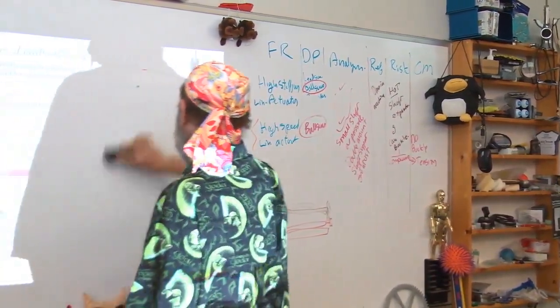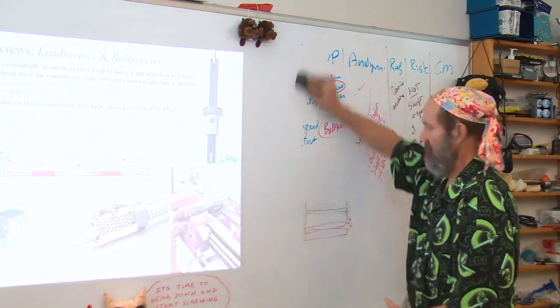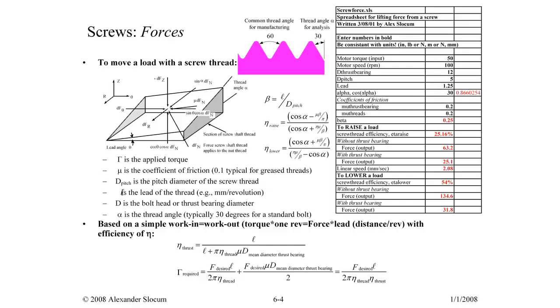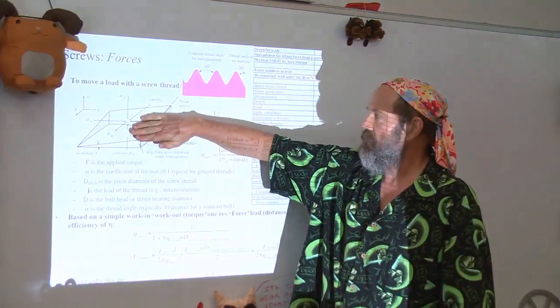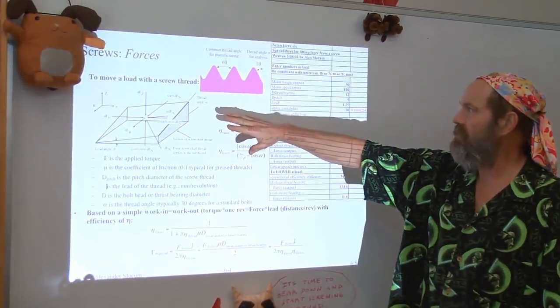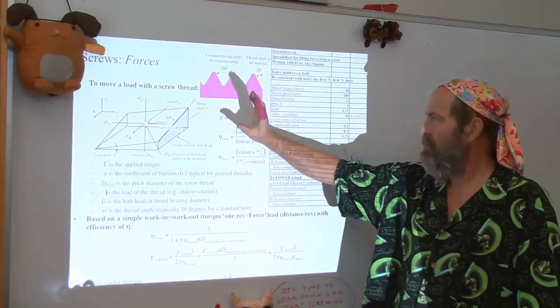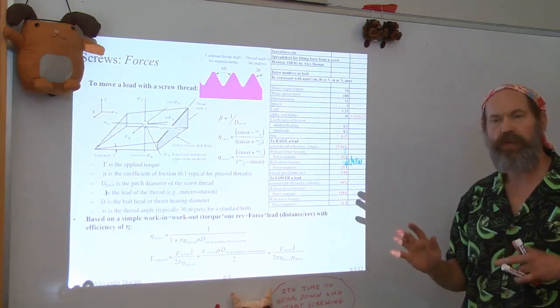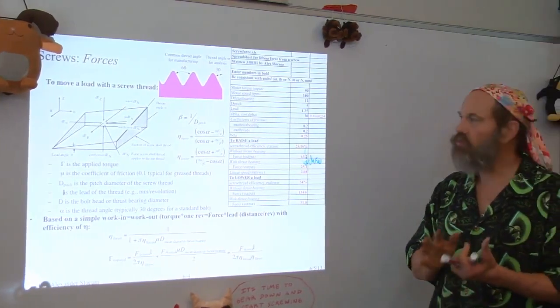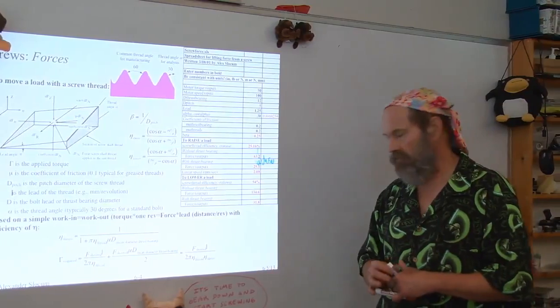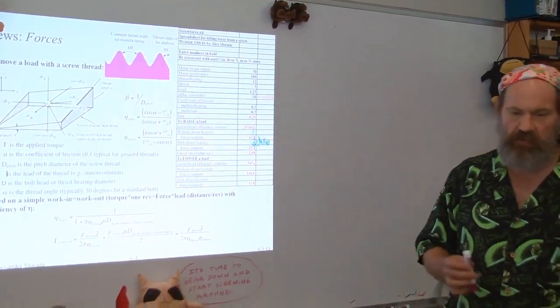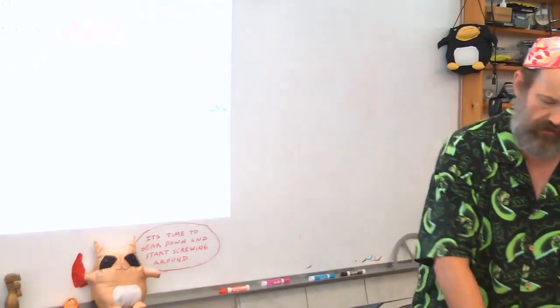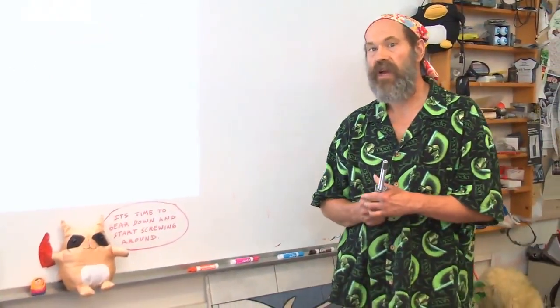So let those thoughts simmer here for a minute while we start thinking in even more detail about the forces that you have to deal with. When you start looking at the screw thread itself and the types of angles and what the forces look like, you can actually calculate, given just the coefficient of friction between materials, the screw efficiency. That calculation is well known how to do that. And even more, it follows that you can calculate, is the screw back drivable or not?